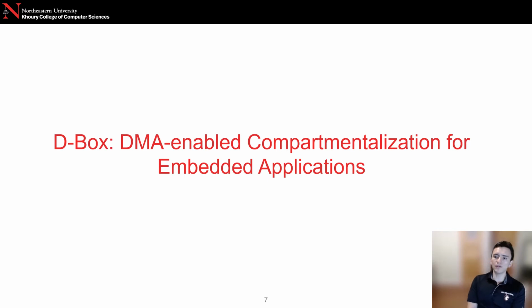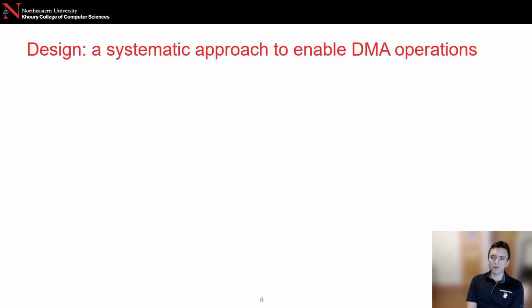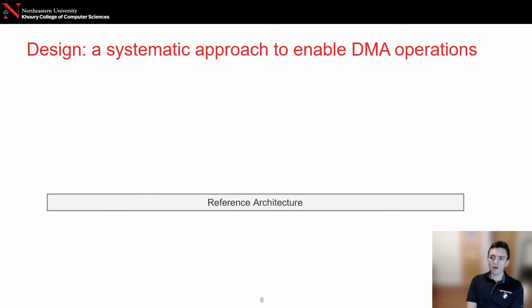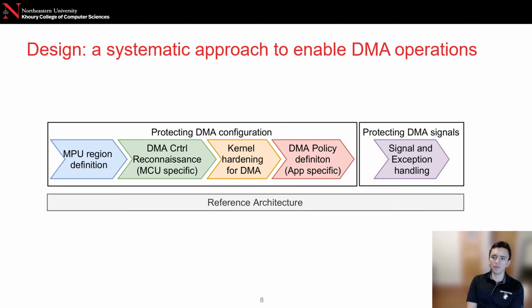To solve the current limitations, we introduced DBOX, DMA-enabled compartmentalization for embedded applications. DBOX defines a reference architecture and a systematic approach to enable DMA operations. Our approach includes procedures for MPU region configuration, DMA controller reconnaissance, kernel hardening, DMA policy definition, and signal and exception handling.